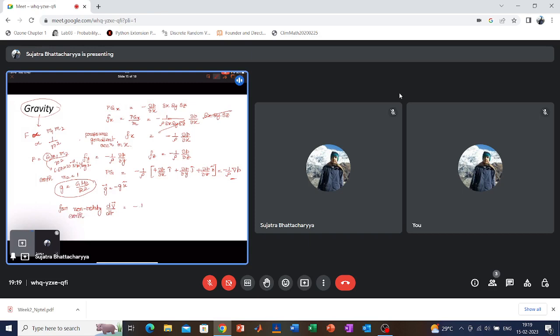So it will be minus 1 by rho grad p, one of the real forces, plus the gravity, which is nothing but in the k cap direction. Another term that comes is the frictional force. This frictional force I will discuss in the next problem solving session. The viscosity kind of concepts will be applied there. So this is the momentum equation.